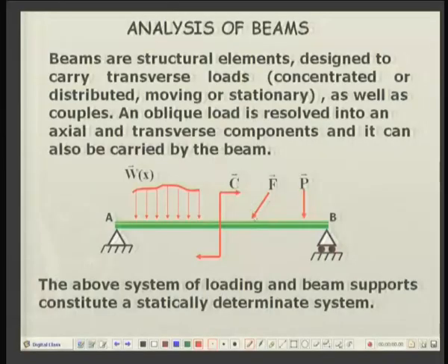Now, if there is an oblique load, as I have shown over here, an oblique load can be resolved into 2 components, a horizontal component and a vertical component, or an axial component and a transverse component. So, the axial component will produce tension or compression, whereas the transverse component will produce bending, okay, as we will see later on.